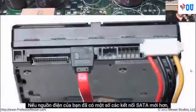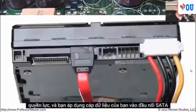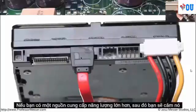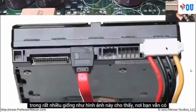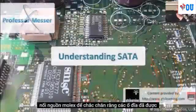If your power supply had some of the newer SATA connections, you would simply plug the power connection into the SATA power, and you would plug your data cable into the SATA connector on the drive. If you have an older power supply, then you would plug it in very much like this picture shows, where you still have the same data connection, but you would use this legacy Molex power connector to make sure the drive was operational.